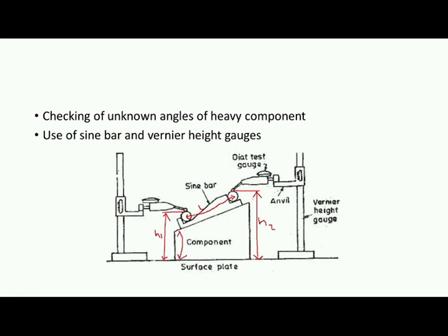So, using that relationship, sine theta is equal to the difference between H2 and H1, H2 minus H1, divided by L. So, using this relationship we can find the taper angle of the component.